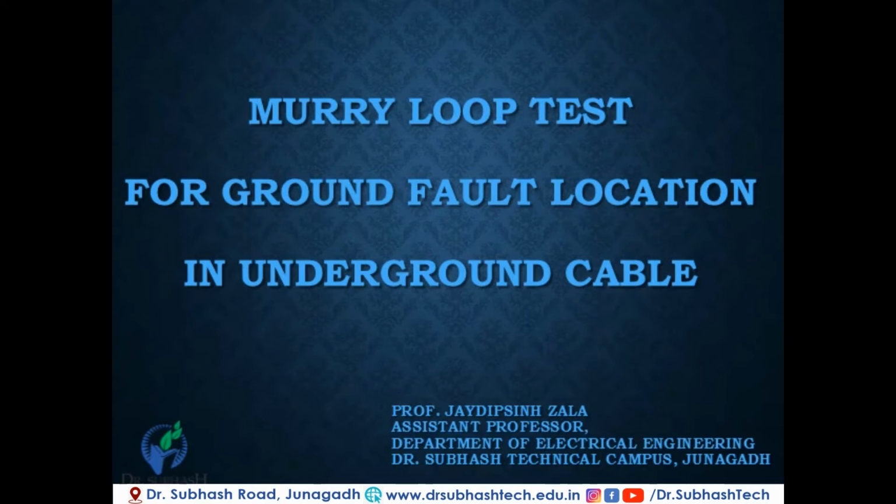As we know, most of today's power transmission has been replaced from overhead transmission lines to underground cable systems. If power transmission is done by overhead lines and a fault occurs, it's very easy to find the fault location and replace it. But what happens when a fault occurs in an underground cable system? It's very difficult to find the fault location and repair it. So here we use the Murray loop test to find the fault location in an underground cable system.